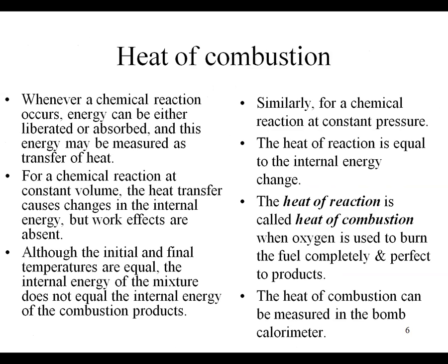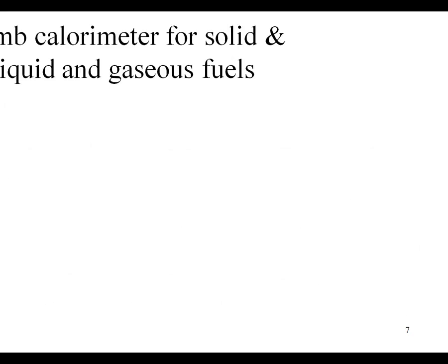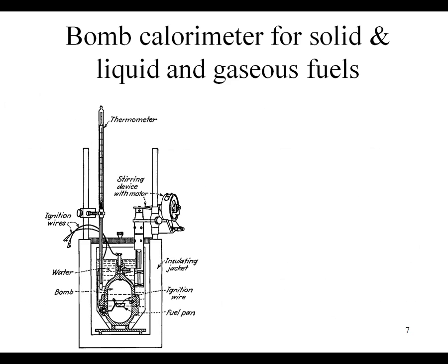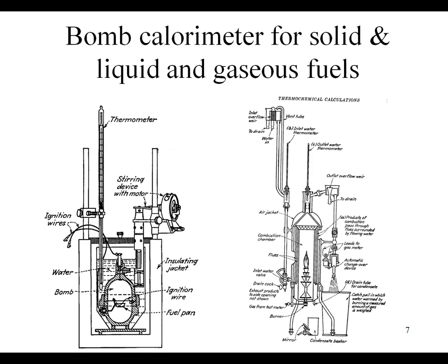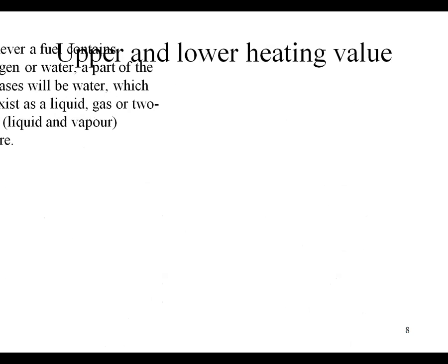To the composition of the fuel. Yes? The heat of combustion can be measured experimentally in a calorimetric bomb, or it can be calculated. This is how such a calorimetric bomb is constructed. This is for solid and this is for gaseous fuel. The idea is that you have to organize the combustion of a known amount of fuel and measure the resulting heat energy. And then this heat energy divided by the quantity of fuel gives you the heating value.